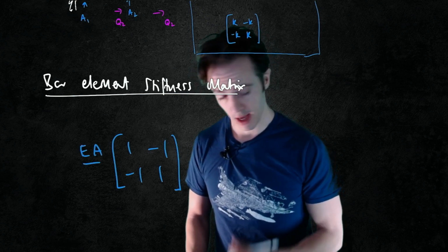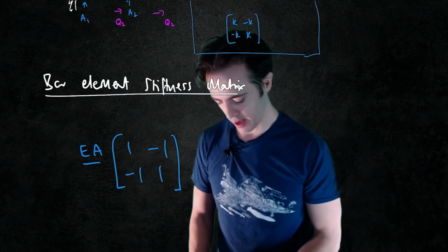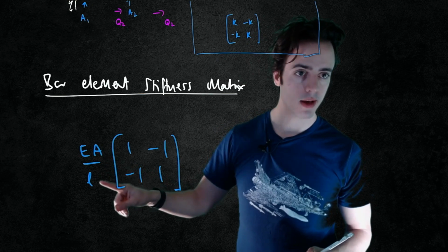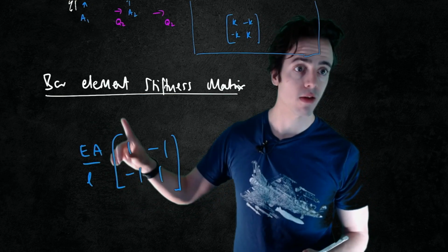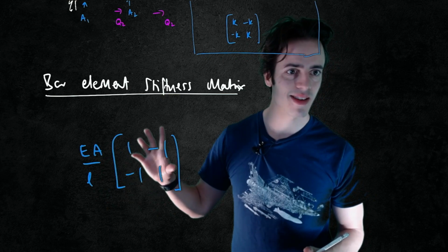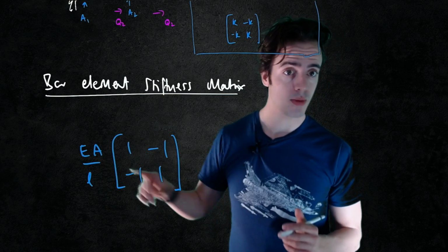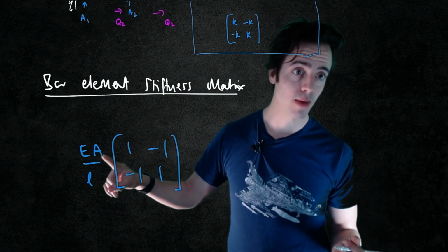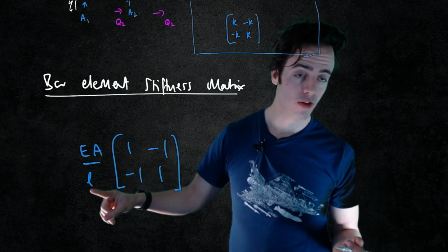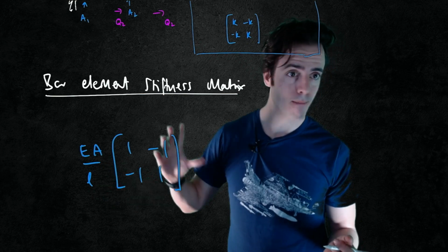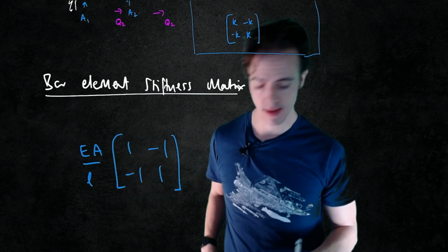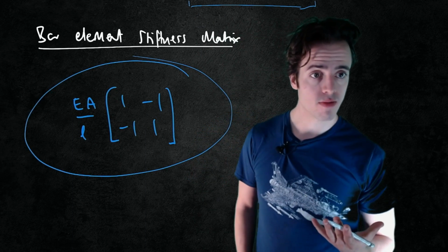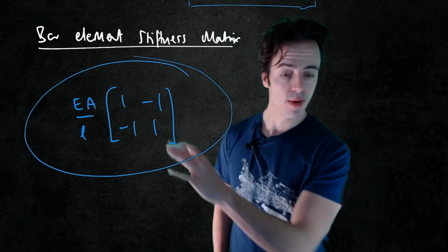Well, since it's a scalar, it doesn't matter whether we pre or post multiply it, by Young's modulus, cross-sectional area divided by the length. And the units of this are the same as what the stiffness should have been, which is Pascal meters, or newtons per meter. So remember, E has units of pascals, A has meters squared, L has units of meters. So this gives us newtons per meter. This is how we've changed the problem to set it up for bar elements instead.